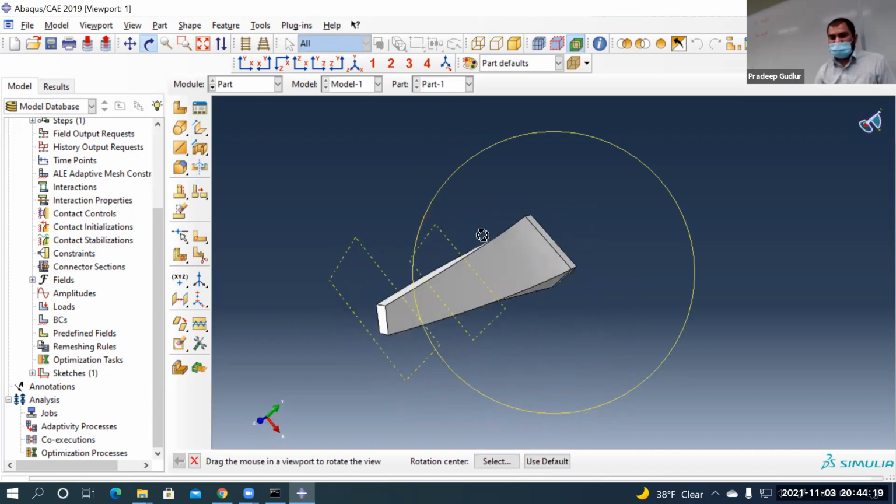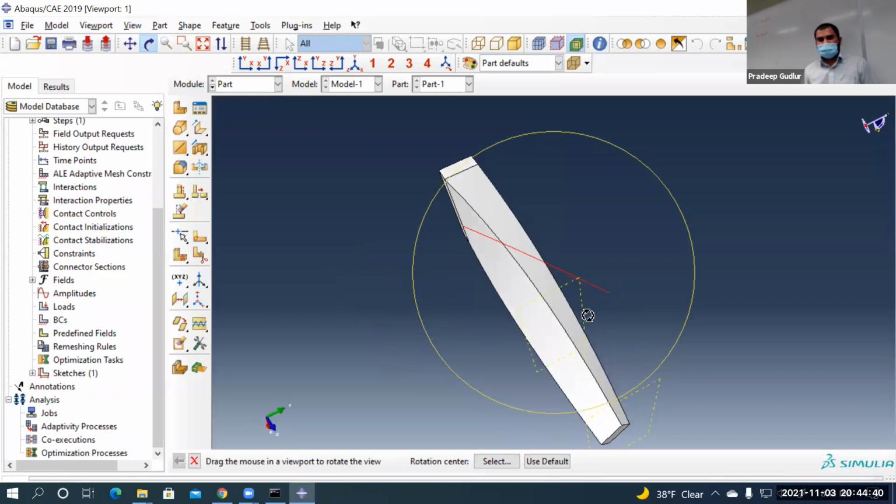If I pick more sections, I can control this twist. You want the blade to be twisted so that air can impact on the surface at any angle and still the blade rotates. It's not a straight section. It has to be slightly twisted. That's why we rotated it.